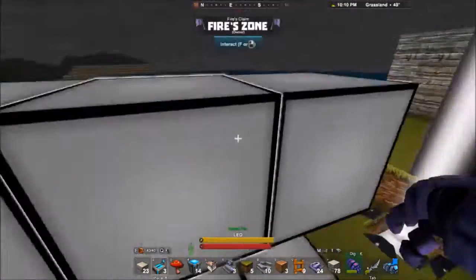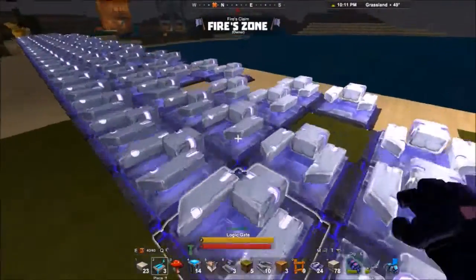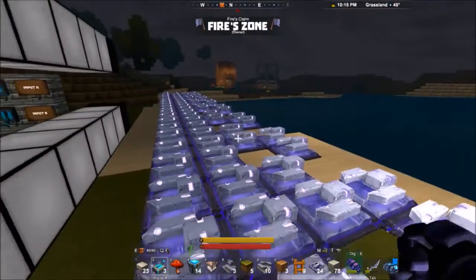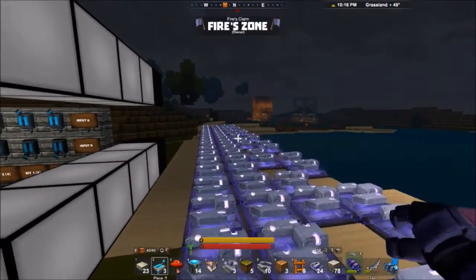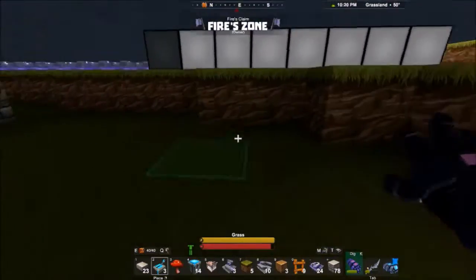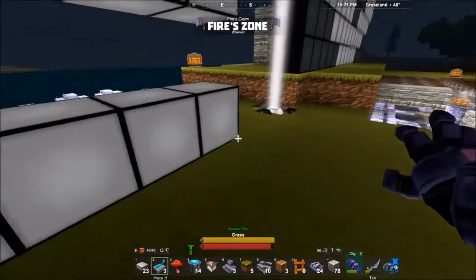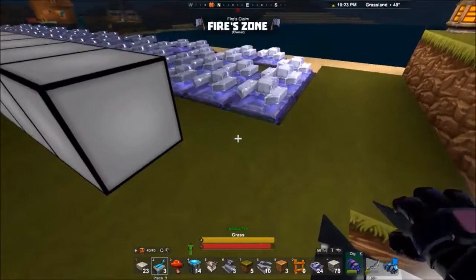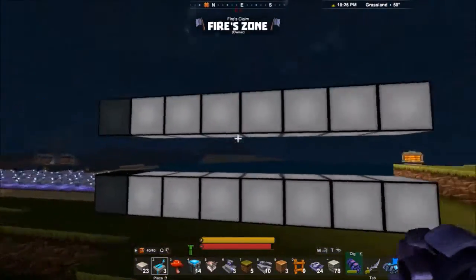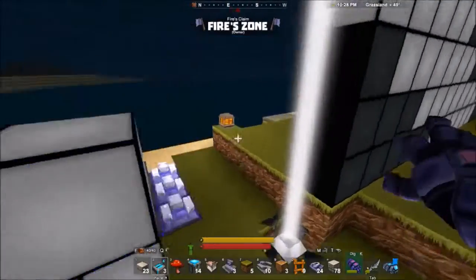This one uses 5 gates per bit, so it's going to be 40 for the whole 8 bits, while the look-ahead carrier is on the 100. I don't even remember how many, but 100 something. So if you think that it's worth it, go for it. This one is way simpler.